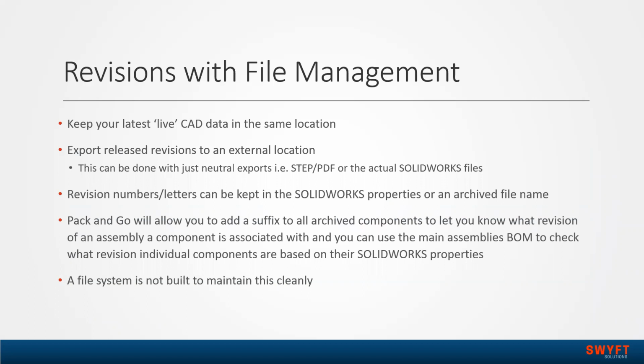But a couple of things to consider. If possible, keep your latest live CAD data in one location and don't change the name, because then you won't ever deal with broken references. If you're going in and adding something like _rev_a to your live CAD data assembly, unless you really are familiar with SolidWorks references, you can break those. If you keep one version, the latest, in one location, you won't deal with those broken references.